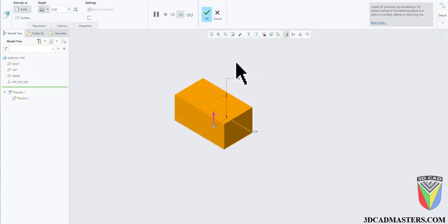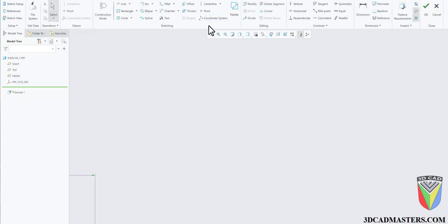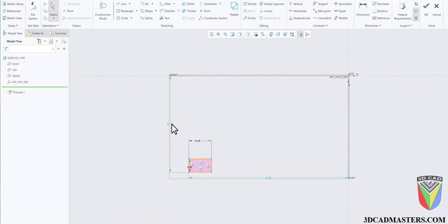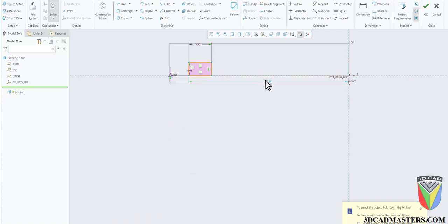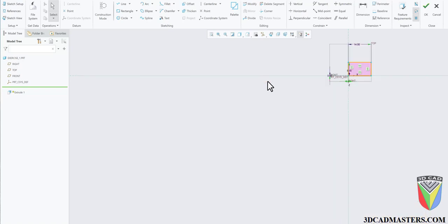Click Dimensions, then click the Placement button. Click Edit the Sketch section. Now you're just going to want to set the positioning dimensions, which are the blue fonts, to 0. And you're done. Now your rectangle is centered.